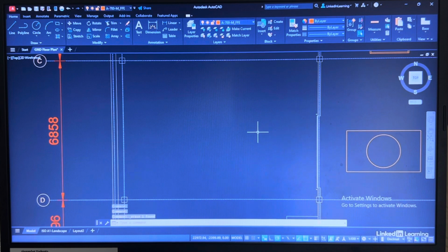So we're going to draw the same polyline, all 4 lines, it's up to you, so that we can see how ortho works. But to do that, I've got to come down to the status bar and turn ortho on here. There you go, ortho mode. It's off at the moment, but notice when I switch it on, polar turns off, like so. So let's draw our table again.